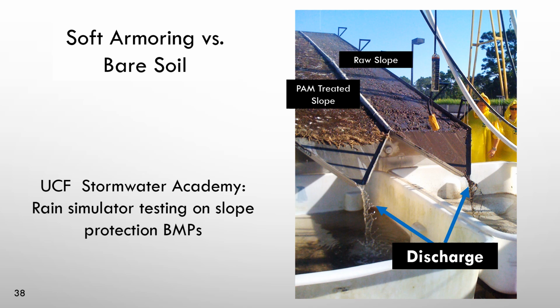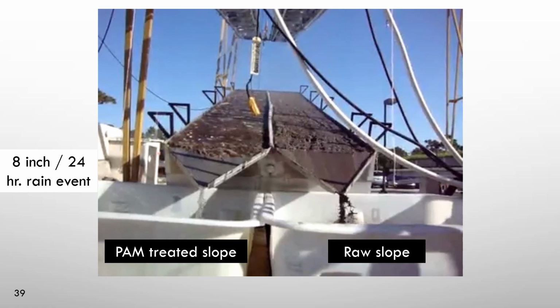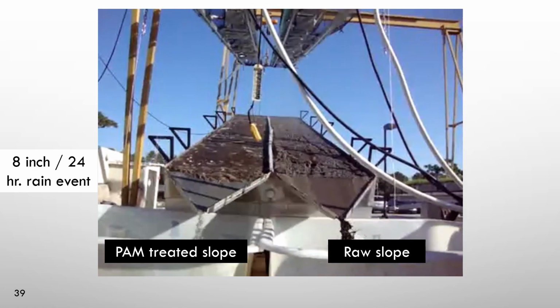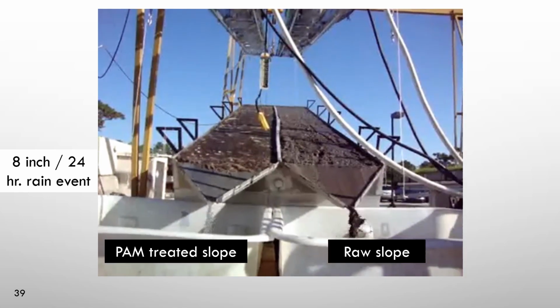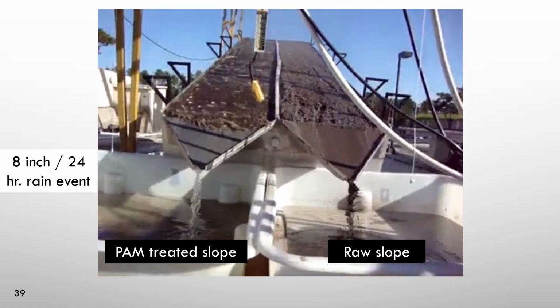And again, the erosion control matting was keeping a lot of the erosion from occurring, but we still had very high turbidity running off because of some of the fine particles in that soil. On the PAM treated slope on the left, we're preventing the erosion and then also improving the water clarity. So they did an 8-inch per hour rain event, and you can see the raw slope on the right. There's erosion, there's very, very high sediment running off that slope. And on the left-hand side, it's relatively clear water.